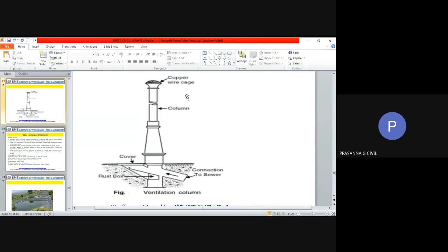Laying is always started from the lower end to the upper end. You need to have the plan. Suppose we are talking about laying the sewer line for a layout. You need to have the exact levels of everything, like we did it. This is the exact thing we were trying to do earlier. You have taken the levels through individual crossroads everywhere. Why? Because you need to know the exact levels there. You know the direction in which the liquid is going to flow depending on the terrain.